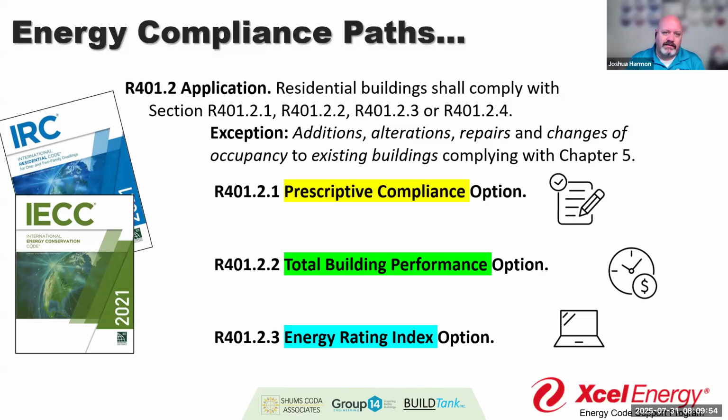And then the third option in residential is that energy rating index. Now, the energy rating index is very similar to our total building performance calculation. However, what it does incorporate is, instead of doing dollar for dollar comparison, it's a grading scale, right? We're going to be looking at it as a point on a scale. Where is your building and where's the reference standard? And did you beat that? Is your score equal to or better than that reference standard? We've talked about ERI before. I think I've got a slide or 2 in here about ERI and how it's different in its reports from what we see in REScheck.